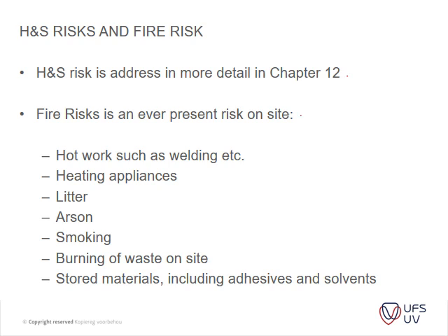A construction site is more prone to fire risk than anything else. Because you have hot work such as welding, blow lamps, cutting and grinding, etc. You have heating appliances on site, especially gas bottles and welfare facilities. Litter, especially in restrooms and drying areas, might pose a risk, obviously.